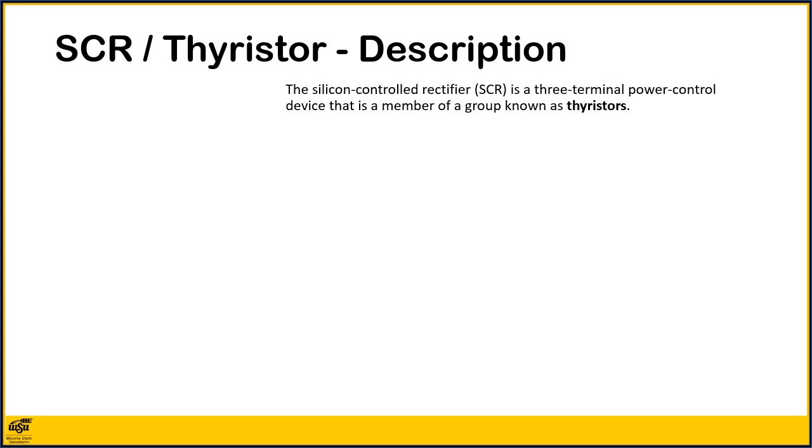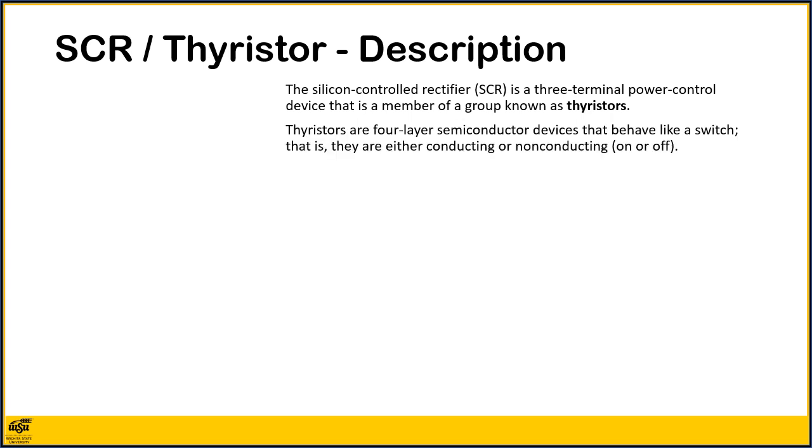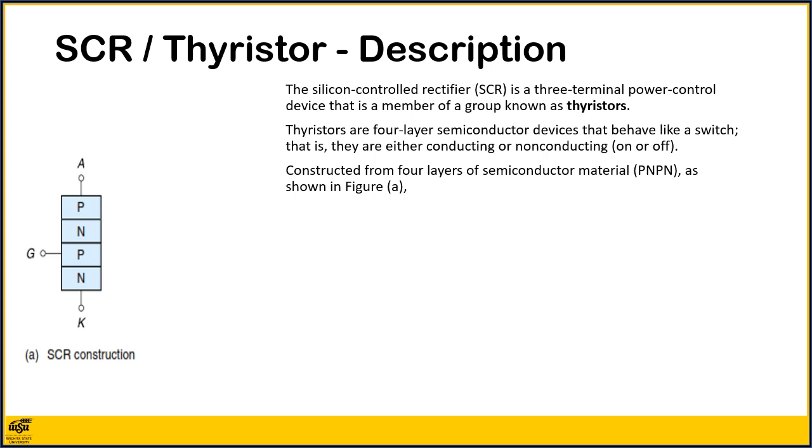The silicon controlled rectifier, or SCR, is a 3-terminal power control device that is a member of a group known as thyristors. Thyristors are 4-layer semiconductor devices that behave like a switch. That is, they are either conducting or non-conducting, on or off.